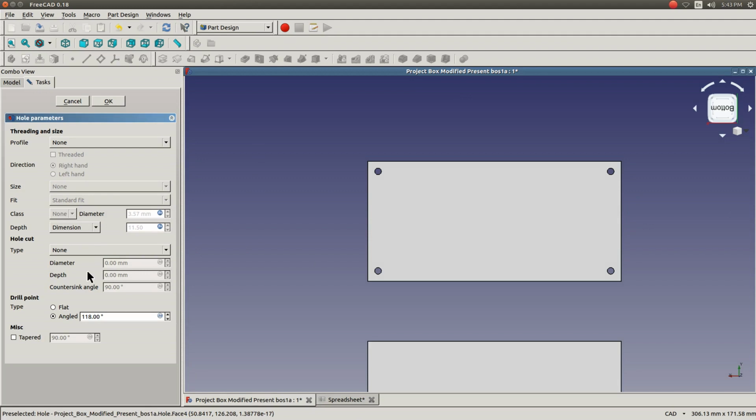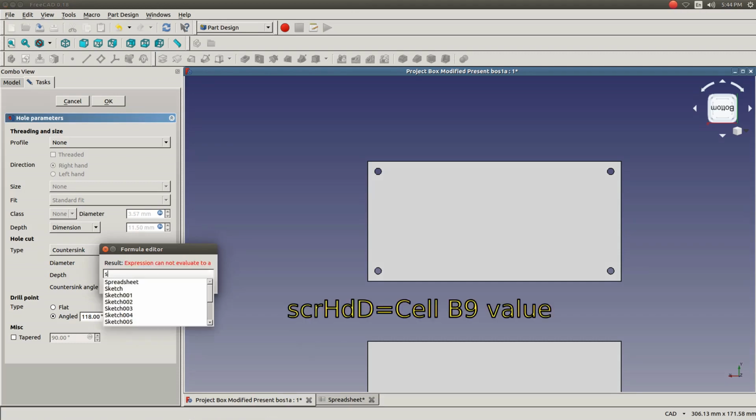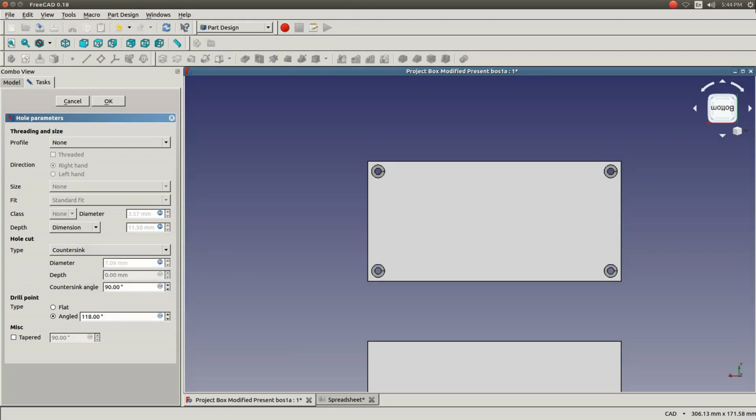Next is our hole cut. First, we'll select countersink. As you can see, we're left with head diameter and countersink angle. Head diameter is simply pulled from column 1 of the sheet. We could also parametrically define the angle as well, but I chose to manually define this. If you live in a metric country, the angle is 90 degrees. Since I live in the US, the angle is 82 degrees. Yes, I know there is also a 100-degree angle, but this is mostly used for fastening sheet metal. Let's set these two dimensions.